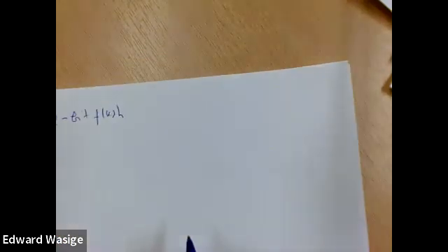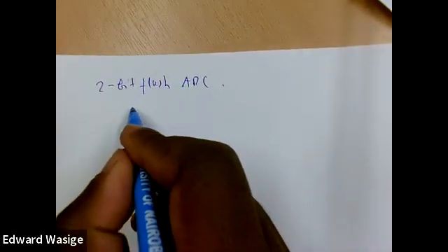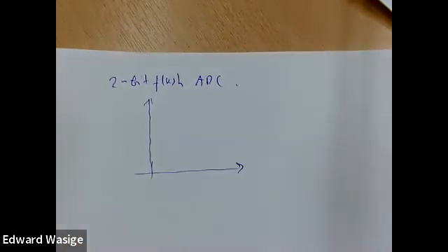So the next question is from Marwan, which is for flash ADC. For flash ADC, why is the top 1.5 and the bottom 0.5? Okay, thanks, Sitong. Yeah, Marwan, that's quite easy. We can do a 2-bit flash ADC. So the best way to figure out the resistance values is to have a sketch of the transfer